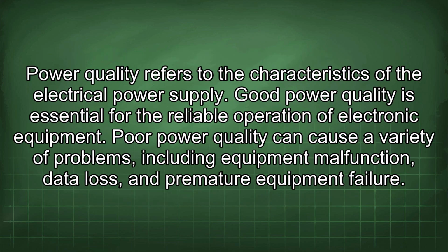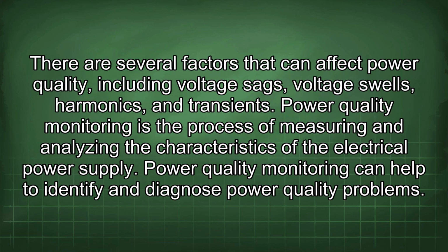Power quality refers to the characteristics of the electrical power supply. Good power quality is essential for the reliable operation of electronic equipment. Poor power quality can cause a variety of problems, including equipment malfunction, data loss, and premature equipment failure. There are several factors that can affect power quality, including voltage sags, voltage swells, harmonics, and transients.